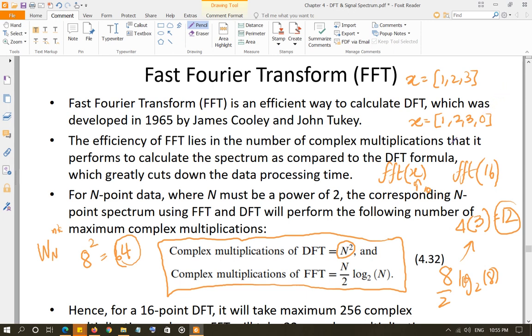Now zero padding does not insert any new information in your signal, because again it's 0. When I say it does not insert any new information, it means it does not include any additional frequency in your signal. Remember, our goal is to find the frequency contents of the signal. When you do zero padding, it does not introduce any additional frequency in the signal. All it does is increase your time t0.